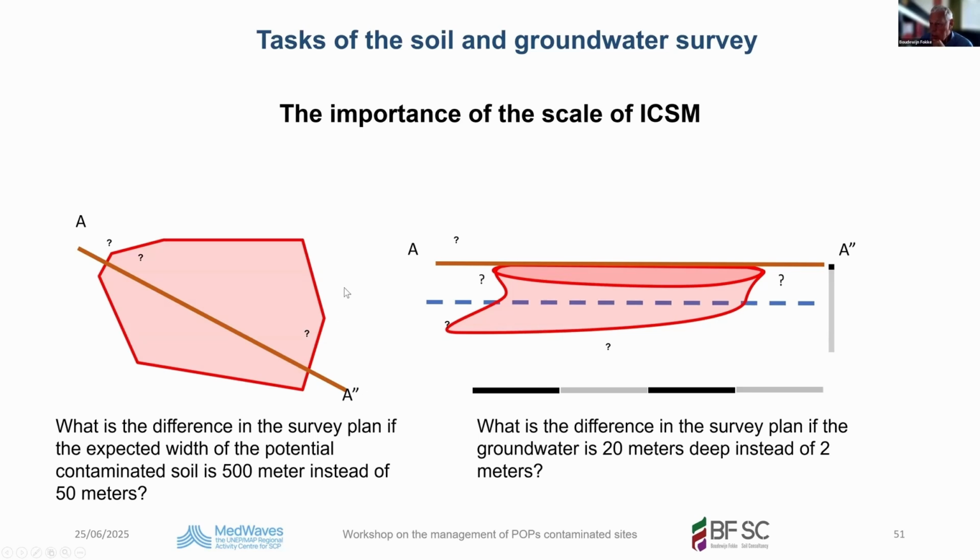If you decide to take a raster of 2 by 2 meters and the scale is not given, you may come to excessive costs. So the scale is a very important aspect, and before you start any investigation, discuss what scale you are going to use.